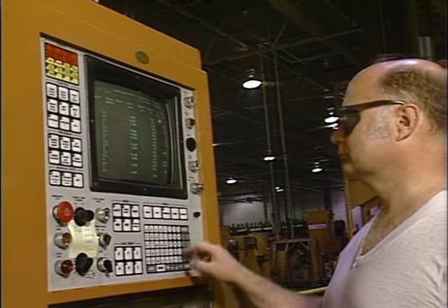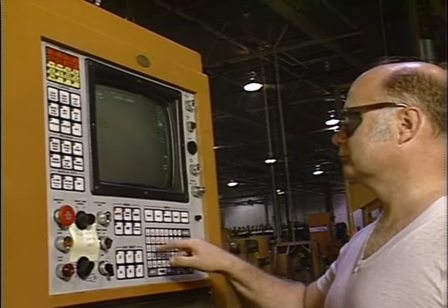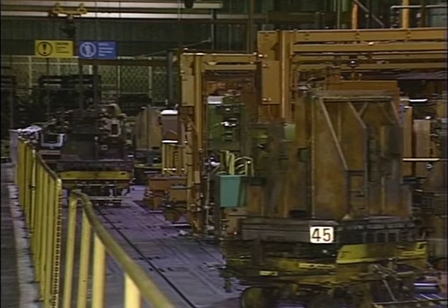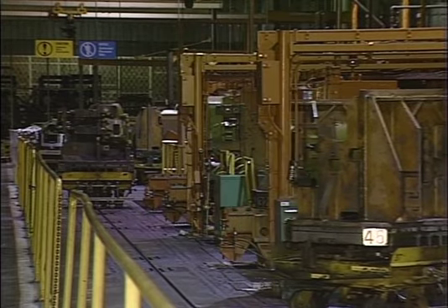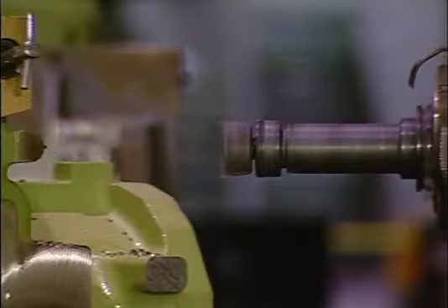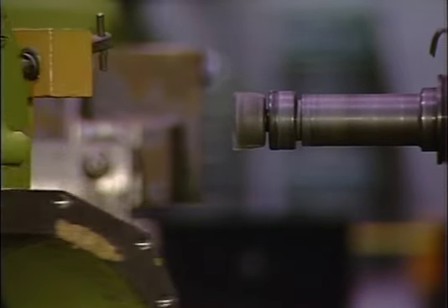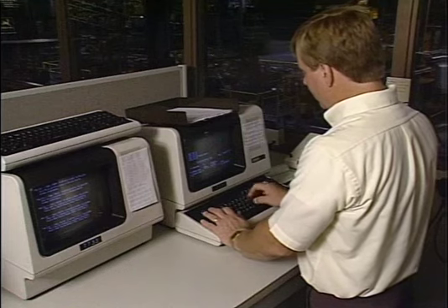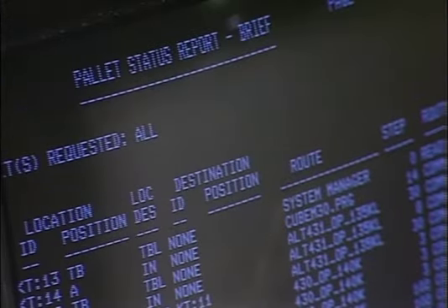Once processing is completed, the machine center notifies the central computer, which then dispatches an AGV to pick up the workpiece and deliver it to the next station. The central computer schedules the flow of parts through the system, efficiently utilizing the machining centers. It monitors tool wear, alerts the operators when tool replacement is required, and is capable of rerouting pieces in case of work center failure.